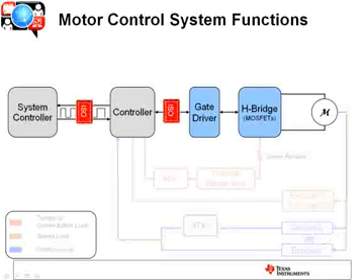These motor systems also typically require isolation circuits, especially at the high voltages when you're in the 300, 400, 500 volt range. That gate driver and H-bridge section is at a very high voltage, and you need to protect that from the low voltage control section, so isolation is required. You can also need isolation to increase the range of those communication protocols, those buses, the CAN, RS-485, especially in these noisy industrial environments. The isolation devices help extend that range by breaking the ground loops and decreasing the noise on the line.